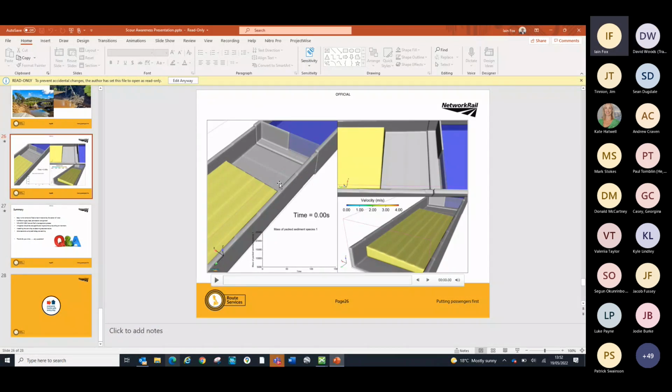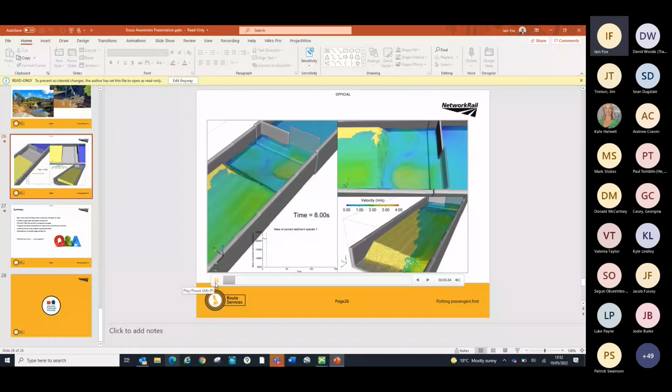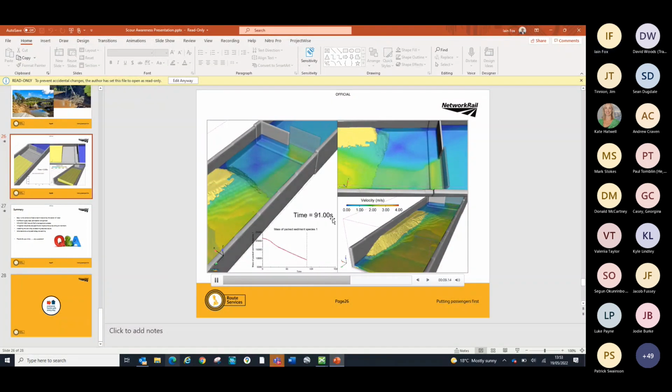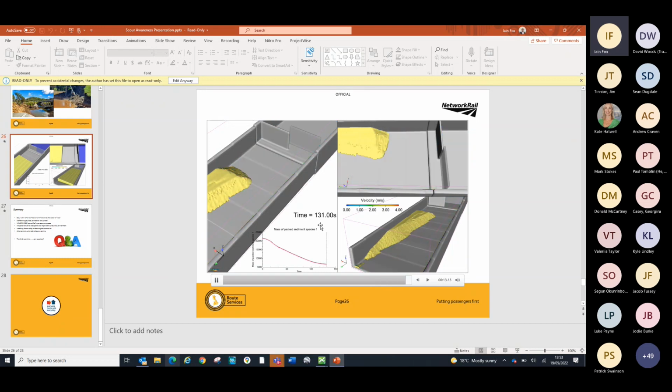Okay, yes, it does. So quick back, sand channel, open 1. So if we open 1 channel and we flood it, you can actually see the sand scours itself away. This is real time. So to clear half of that channel takes just over 120 seconds. That's how fast scour happens.